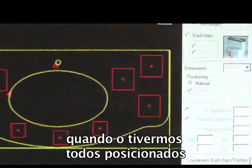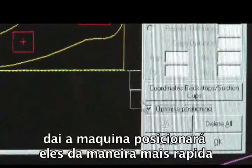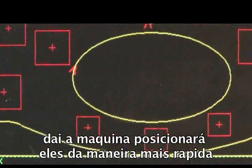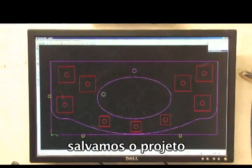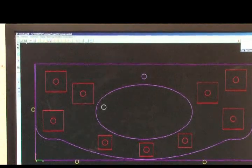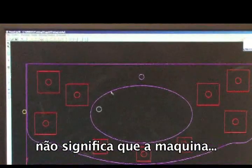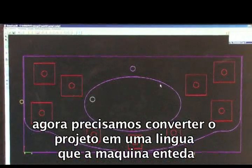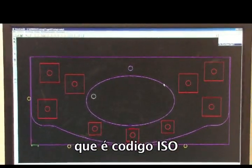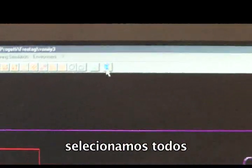Once we've positioned our suction cups, we activate optimised positioning, so the machine will position the cups in the fastest way, and we select OK. Now this is our finished project, and we save the project. By saving the project though, this doesn't mean the machining's finished, because now we have to convert the project into a language that the machine understands, which is ISO code. For that, we proceed to generating the ISO program.